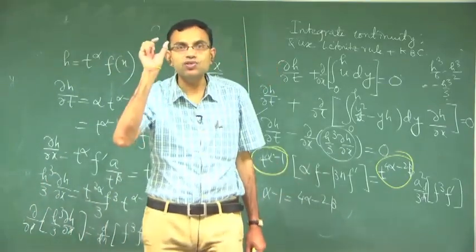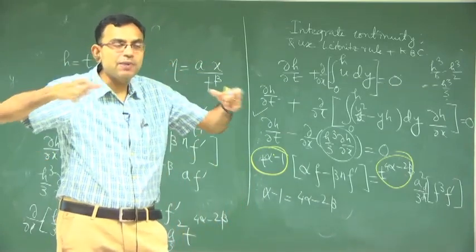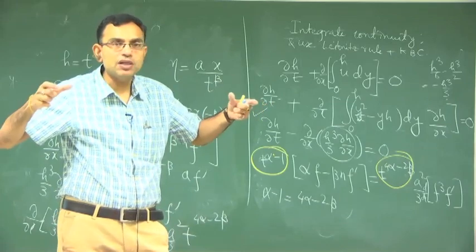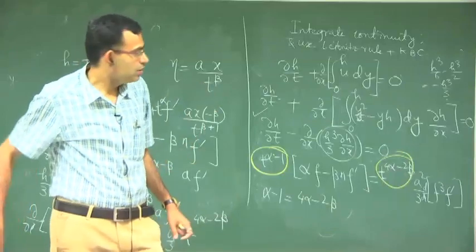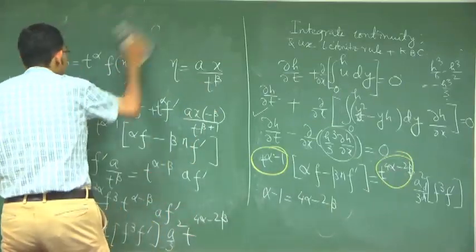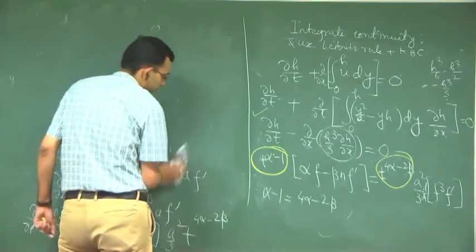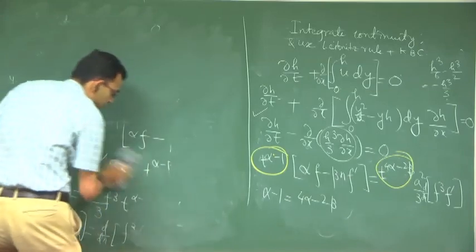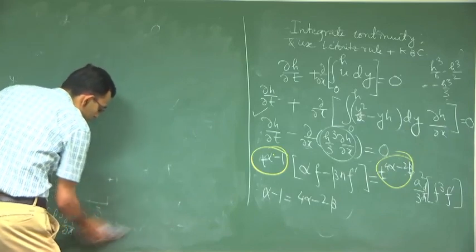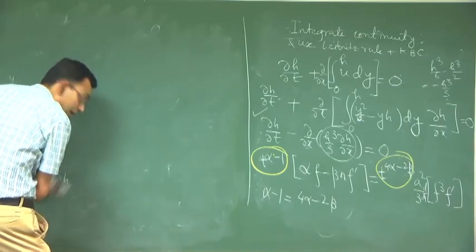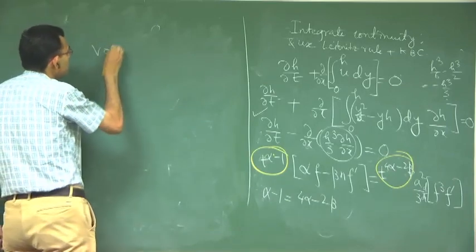We have not used another very important physical constraint, that is, whenever the droplet is spreading, in the absence of evaporation, what is remaining conserved is its volume. So, the constraint is volume conservation. If you are modeling evaporation, you can put a modified volume constraint taking into account the evaporation flux, but otherwise the volume conservation.